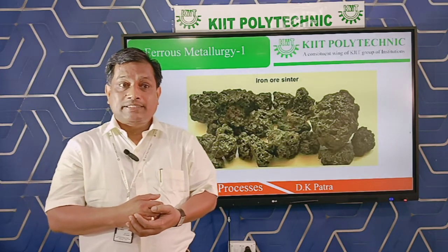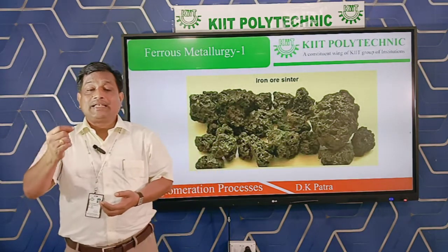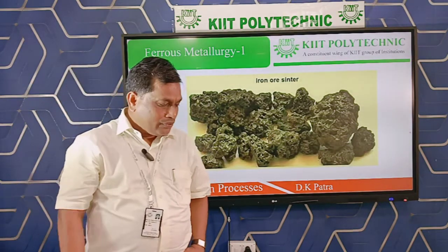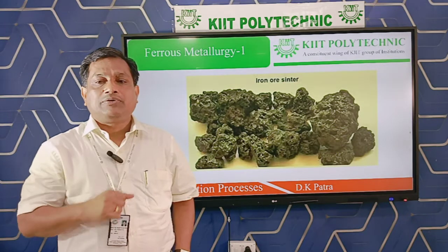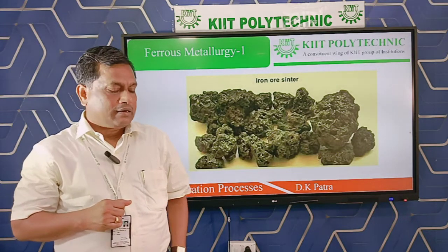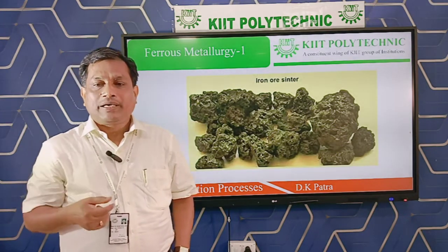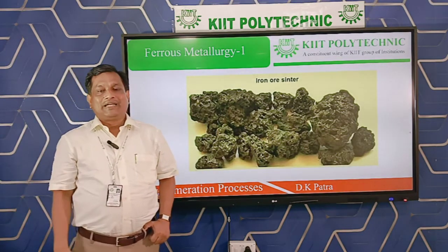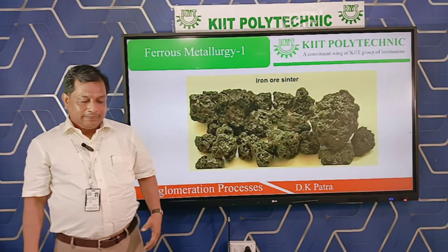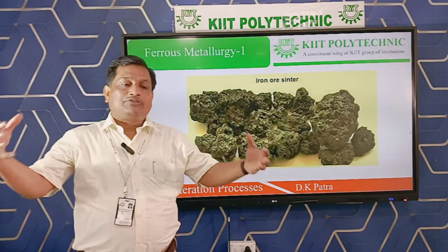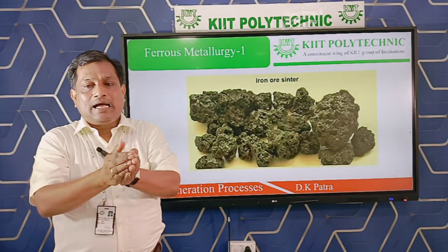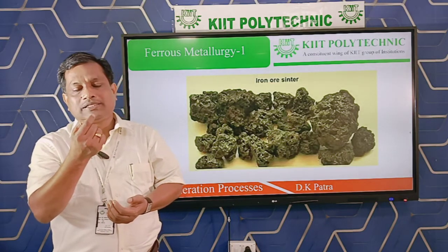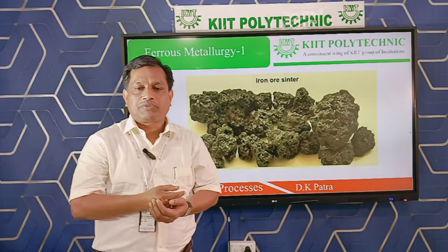What is this pelletizing? The pelletizing process is generally used for very fine particles, say the fines generated during ore dressing operation, that is less than 0.05 millimeter size. That is what can be used in the pelletizing process. Here again we have to unite these fine particles and present them in a granular form, or a nodular form, small balls.